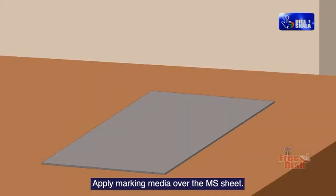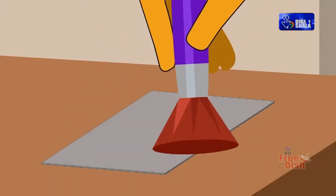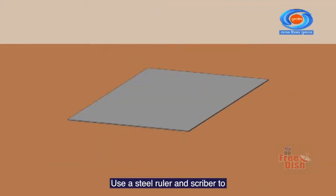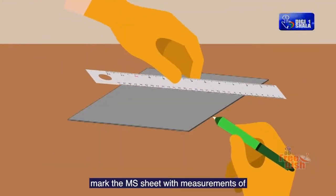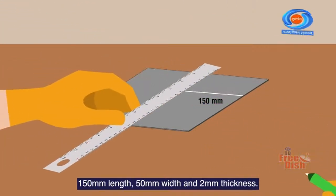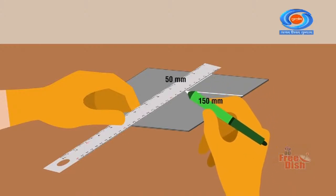Apply marking media over the MS sheet. Use a steel ruler and scriber to mark the MS sheet with measurements of 150 mm length, 50 mm width and 2 mm thickness.